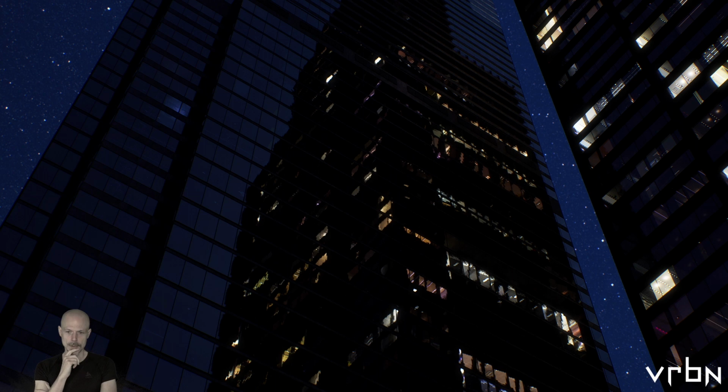Then this is another image that we made, and the context here is the image is made in Unreal Engine. So Unreal Engine is a game engine. And because of these things, it's actually very common that game engines only render what you see. Now, it can happen that, let's say, if you have a reflection of the other side of the building in a skyscraper here, depending on which game engine you're using, it will not actually show the backside because you're not specifically looking at that other geometry because it's hidden. So one of the terminologies there is backface culling, for example, and there are also other techniques like occlusion culling and so on to basically hide everything that you don't see.